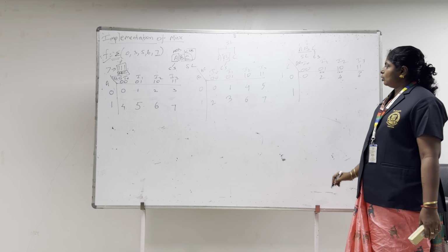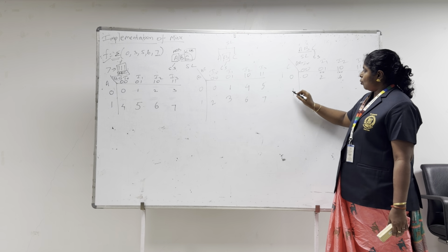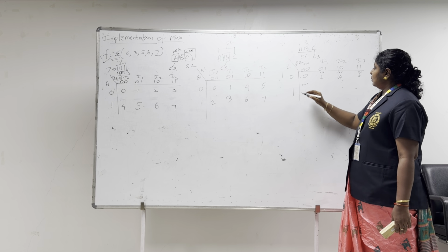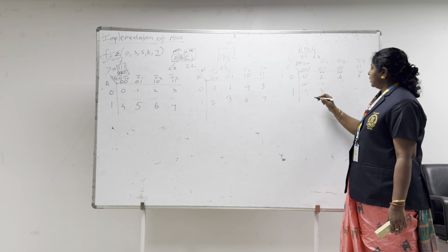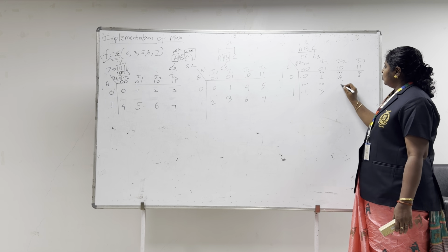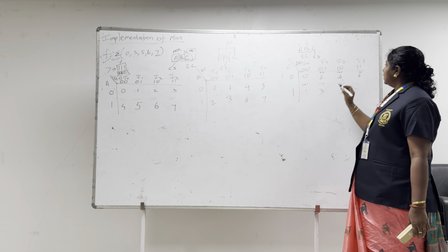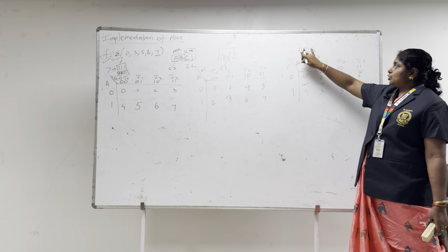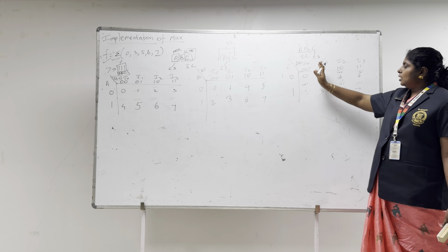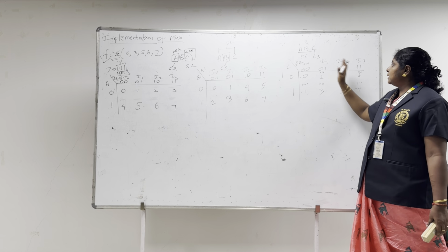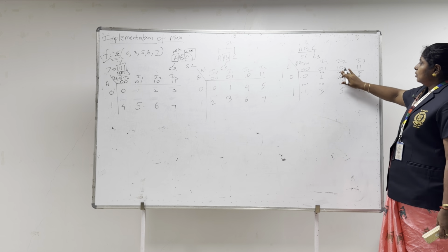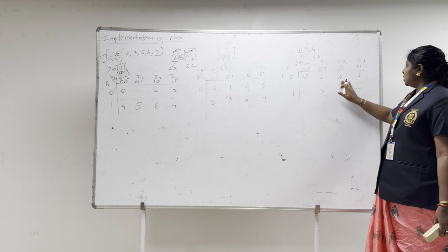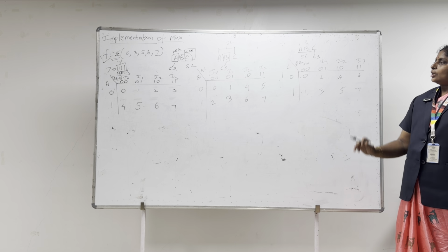I think you can follow it. Similarly over here 0 0 1 is 1. Over here 0 1 1 is 3. Similarly 1 0 1 is 5. Here it is 1 1 1, which is nothing but 7. Okay, so the position of the alphabet variables shouldn't be changed. Just by choosing the control signal, these things will get rearranged, reshuffled. Okay, so this is the format. These are the three possibilities of implementing the mux for this particular problem.